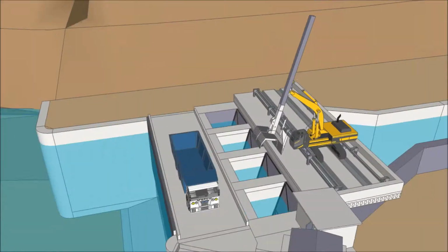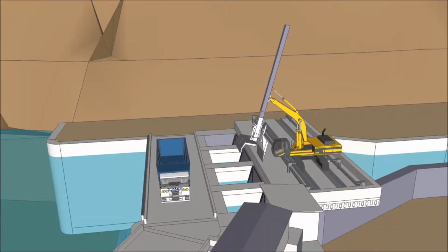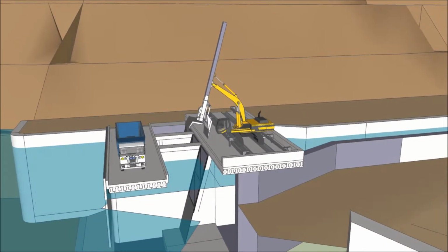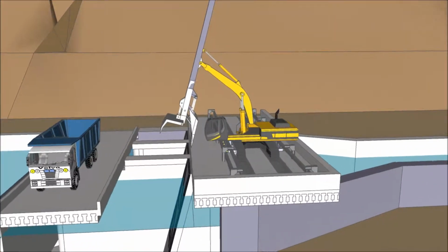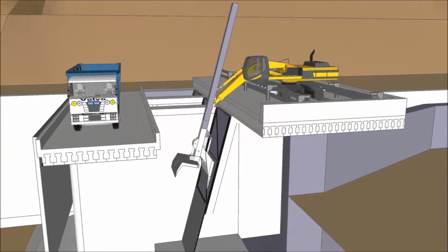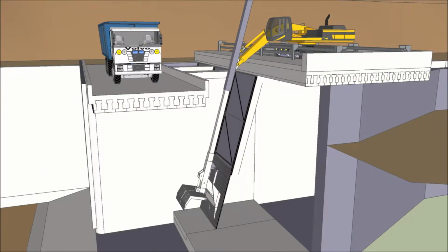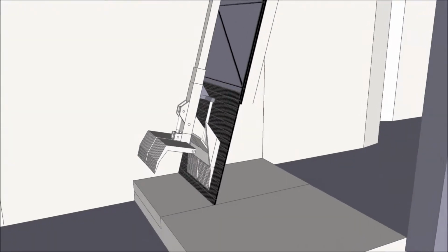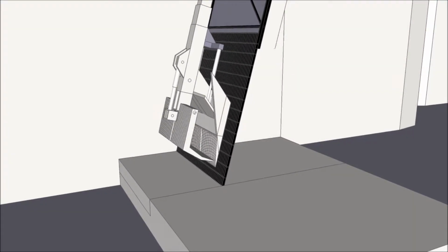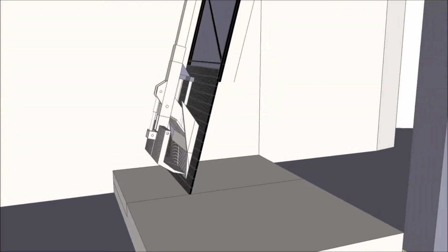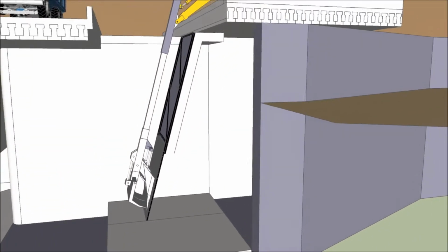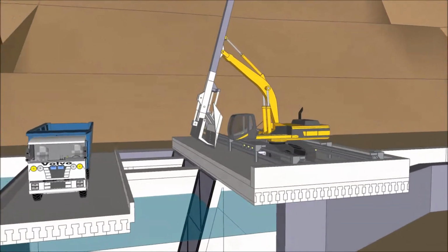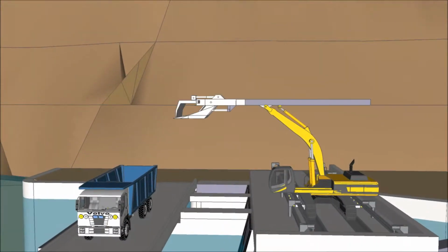Now we will take a closer look at the operations of the working machine. The arm is a marine-grade telescopic arm. It's attached to a standard boom. It's a 2-piece, entirely hydraulic arm, which increases the power, speed, and durability of the component. The lower teeth of this grab shovel act to pry material off of the face of the trash rack, as well as penetrate into the thick debris. The upper teeth secure the shovel load as we move the shovel back up to the top.